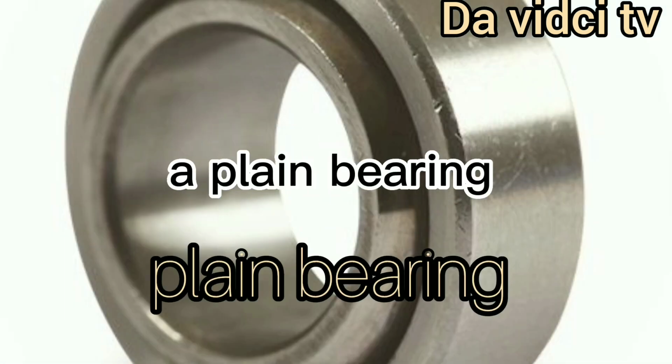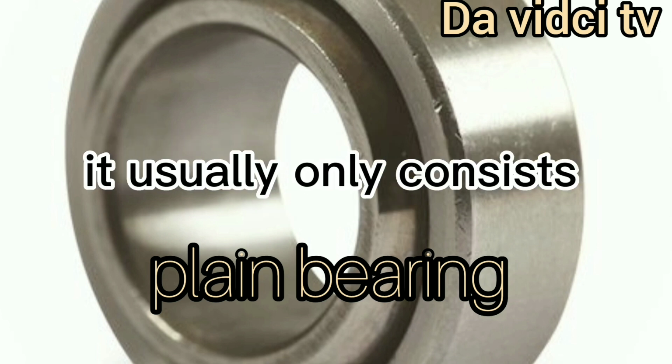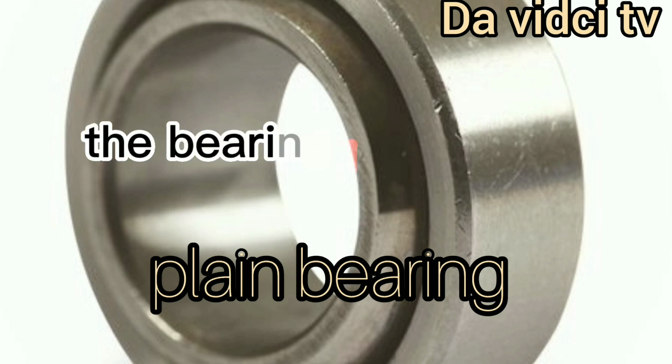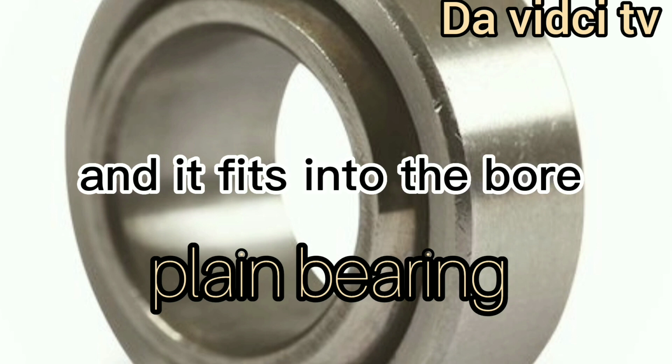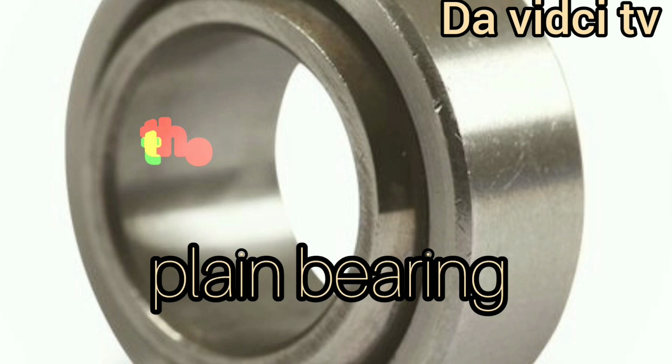Plain bearings. A plain bearing is the simplest type of bearing. It usually only consists of a bearing surface. There are no rolling elements. The bearing is basically a sleeve mounted on the shaft, and it fits into the bore. Plain bearings are inexpensive, compact, and lightweight. They have high load carrying capacity.